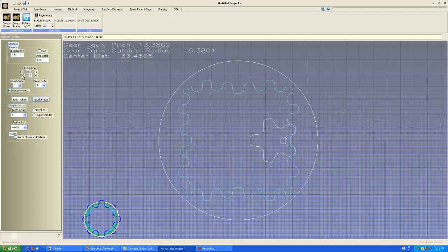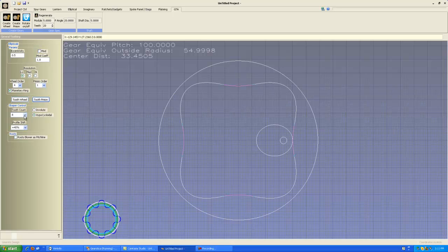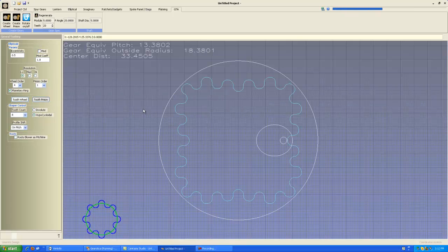So let's first of all shift this to low res. We'll turn off the profile shift by putting the shaper back on pitch, and then we'll try it again. Incidentally, it does you no good to change the shift profile on a round-toothed gear. It's really only applicable to an involute. And we'll tooth the pinion. And then we have 2 gears that probably would work fine.